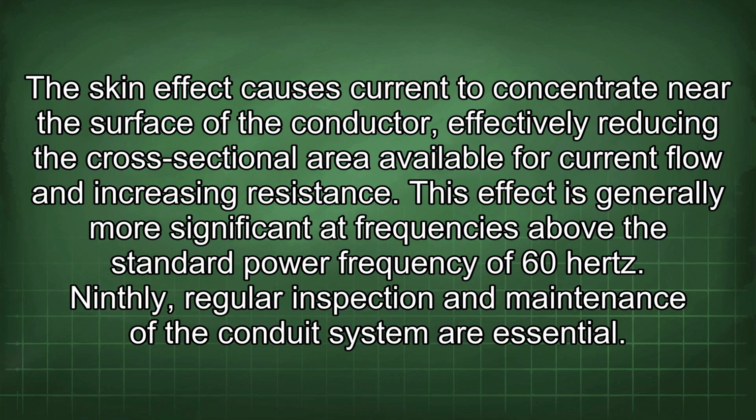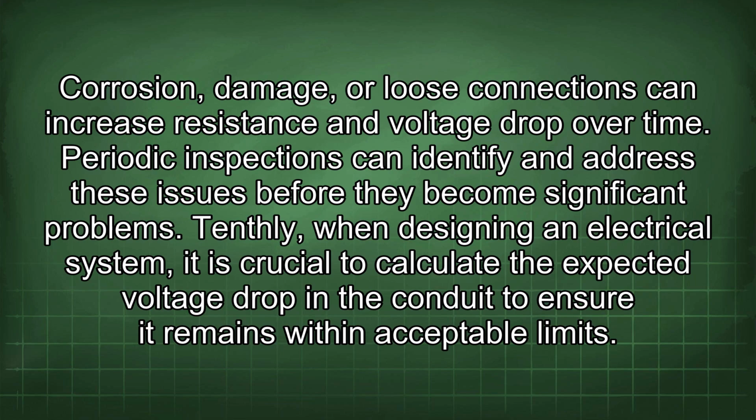Ninthly, regular inspection and maintenance of the conduit system are essential. Corrosion, damage, or loose connections can increase resistance and voltage drop over time. Periodic inspections can identify and address these issues before they become significant problems.